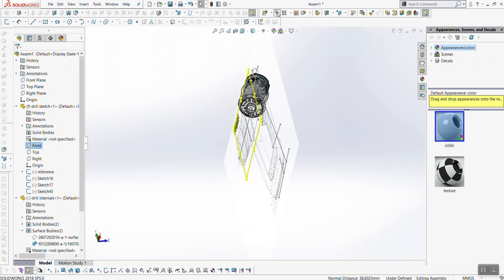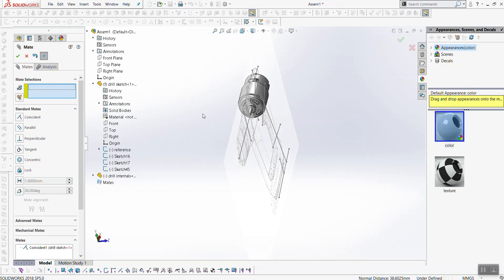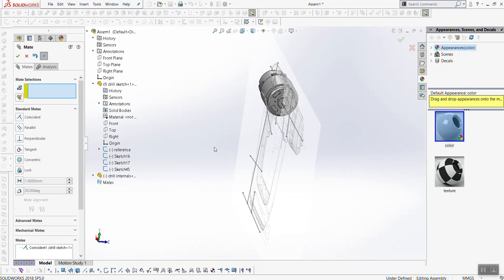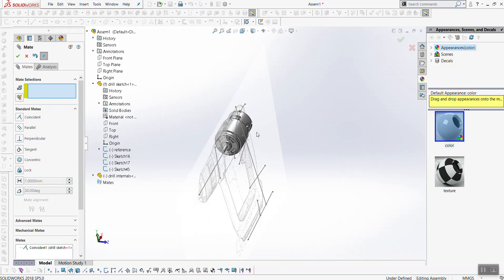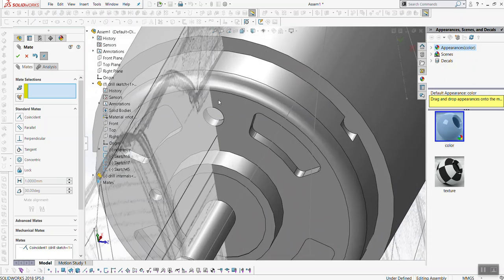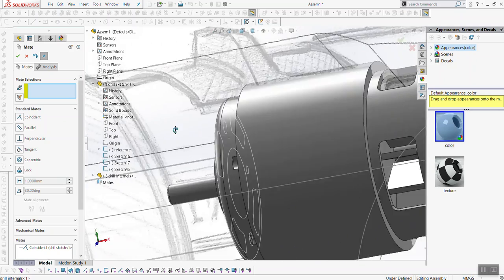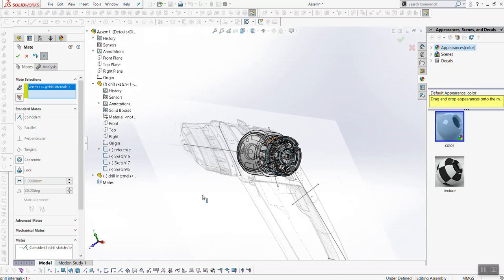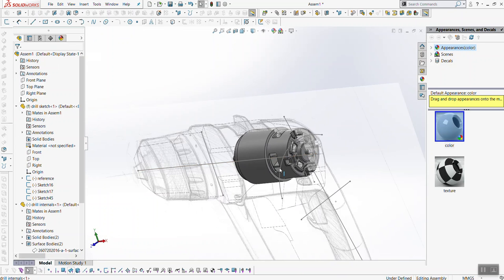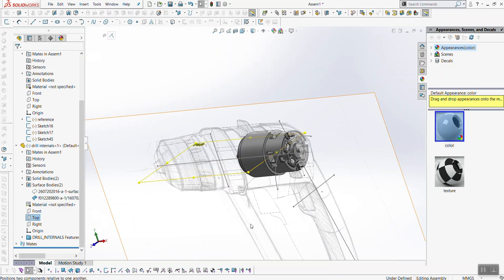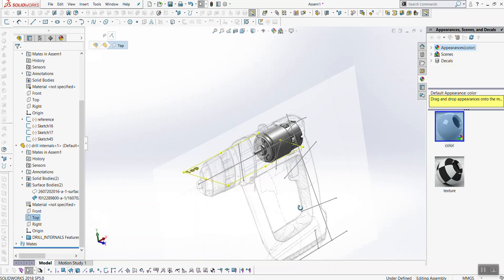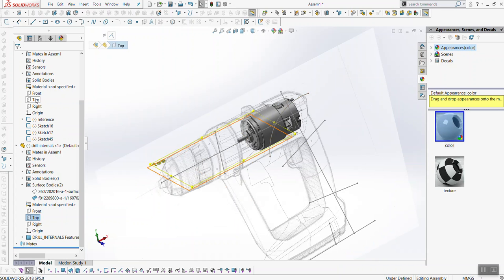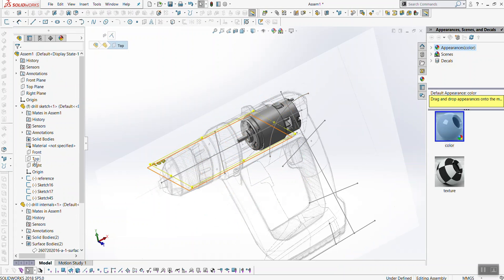And depending on the part files from GrabCAD, if it's from a different CAD program, sometimes you'll find that it's not built on the origin. So you may sometimes need to find the center here by finding the center line and mating that center point to a plane, for example. And that's really important because, again, you want to always be building on the origin. You want these part files, the gut files, to be aligned correctly.